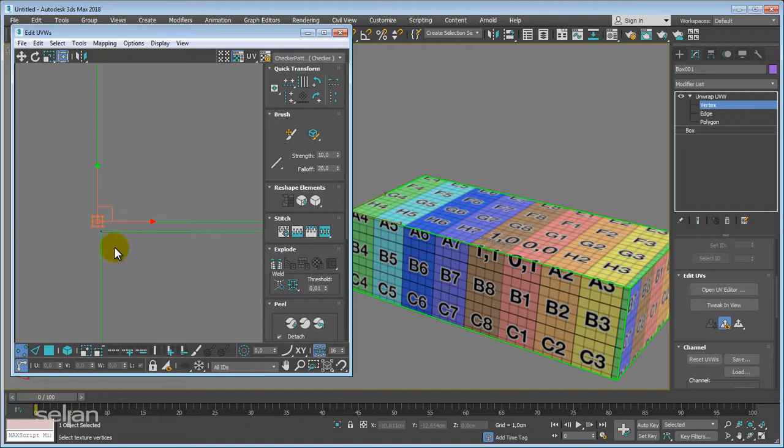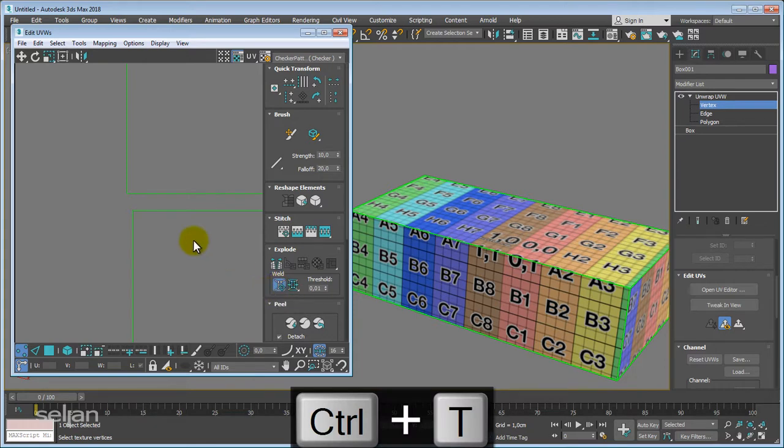These dots are pretty much tiny, but the selected point, this one, is picking its pair. This pair is the blue one. Okay, so when I'm selecting this point, it recognizes that its closest connection is this blue point. So what we have to do is keep the vertex mode on using the target weld. There's a hotkey for target weld just to make it a little bit easier. It's Control T.